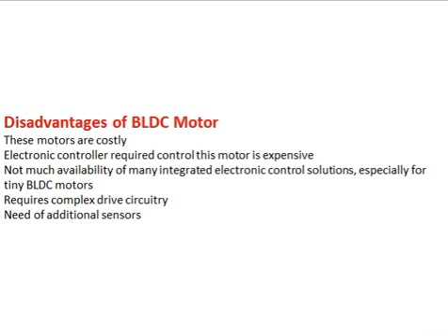Disadvantages of BLDC motor: these motors are costly. An electronic controller is required for control. This motor is expensive. Not much availability of integrated electronic control solutions, especially for tiny BLDC motors. Requires complex drive circuitry. Need of additional sensors.